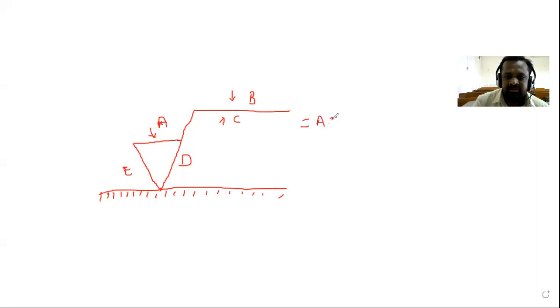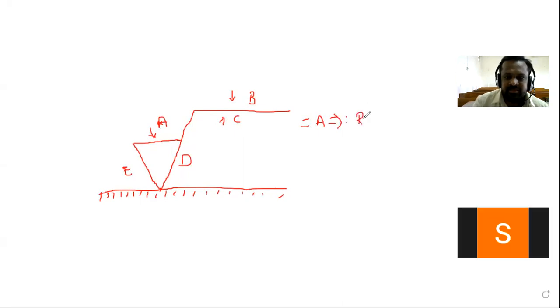What does that A indicate? That A indicates the roughness value. Then that B indicates the production method. Then that C indicates the sampling length. Good, sampling length. What is meant by the sampling length?